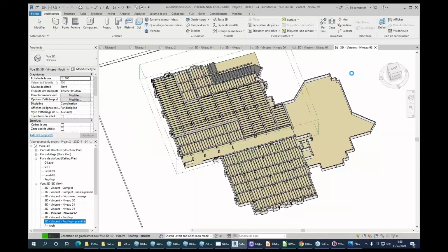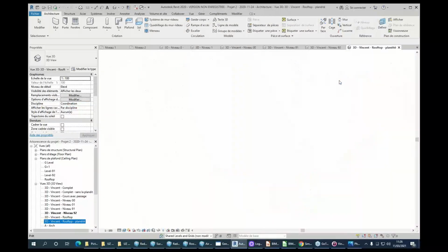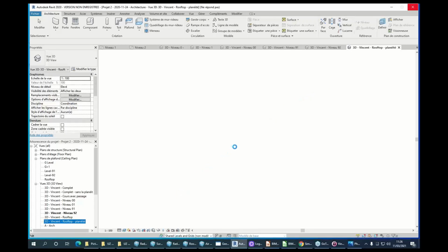So into Revit, we imported the wireframe using a script, and we were able to model exactly the same thing into the BIM model. I'm just displaying on screen. That was an interesting point for that customer, because the flatness was not something they knew how to do, and they wanted something simple, without using a total station and such, something that was easy to do in not a lot of time.